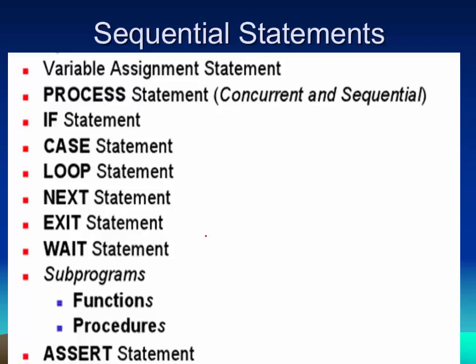But let me talk about sequential statements. If you use a process, that means everything within that process is done in a sequential fashion like a computer program, and it is only done when something occurs in what they call the sensitivity list. We'll see some examples. I have not looked at these slides as carefully, but they should have the examples I'm looking for. We can put if statements. We can put a case statement. If, case.